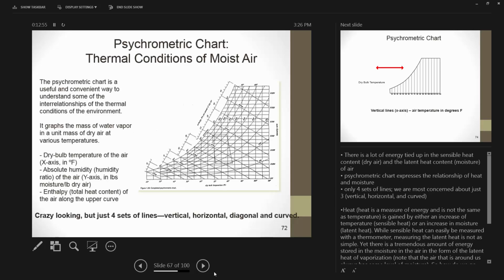And so if you can calculate what the relative humidity is, and by knowing the heat loss, and we talked about calculating conductive heat loss, you can extrapolate what the temperature is going to be inside your wall cavity, so you can determine potentially if the dew point is going to be reached inside the wall cavity.